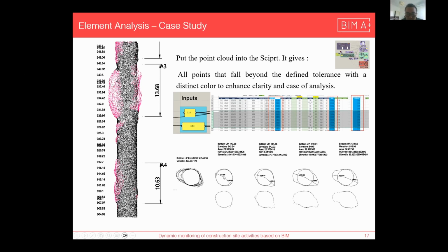And also you can see there's some information about the sections, and this information is the result of integration of the Excel sheet. I talked to the people in the company. They want me to integrate these three columns into the sections. So in the script, I put, for example, column 7, column 10, and column 12 into the sections altogether. So it gave me all the data automatically.